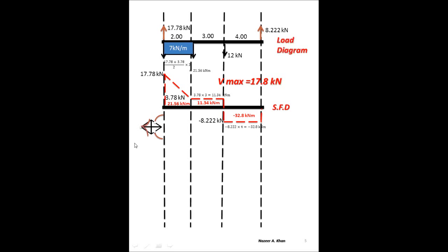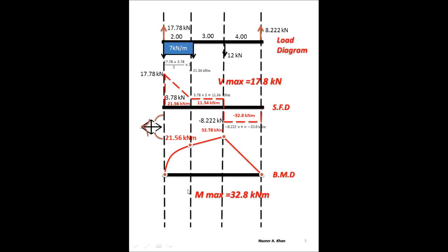I've placed the bug right at that location. You don't have to do this in your work. This is just for me to get the appropriate shape for this particular trapezoid shape when I do the bending moment diagram. As you can see, we know that we're going to have a curve right in there. My triangle is positive, first of all. It's a positive moment, and I have an orientation where my right angle is right there. That is the shape that I'm looking for. So I know I have a convex rising. How much is it going to rise from 0?